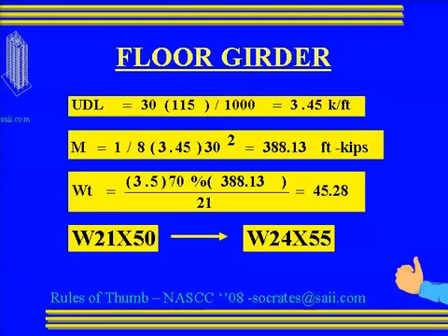21 by 50, you use just 5 pounds more per foot as long as the depth is allowed. You have increased your deflection control by more than 25%. So as usually, for me, when I'm designing, I would make the jump.